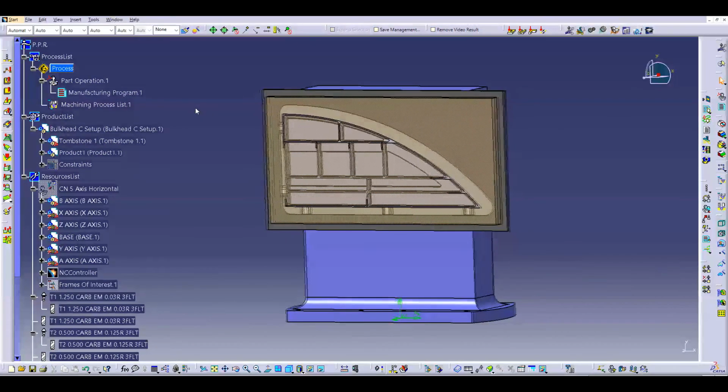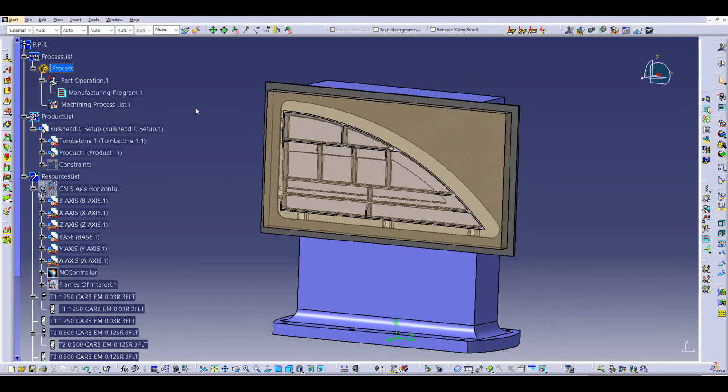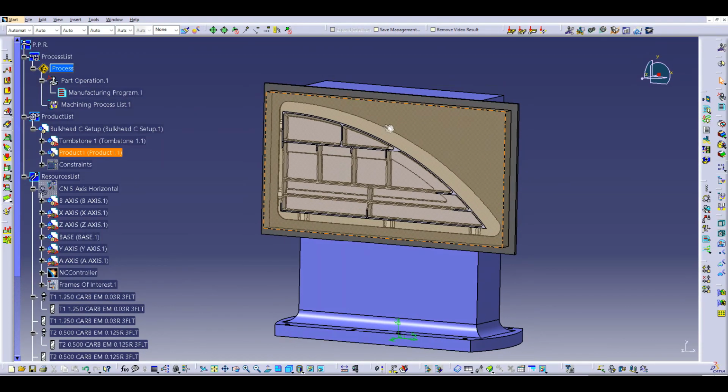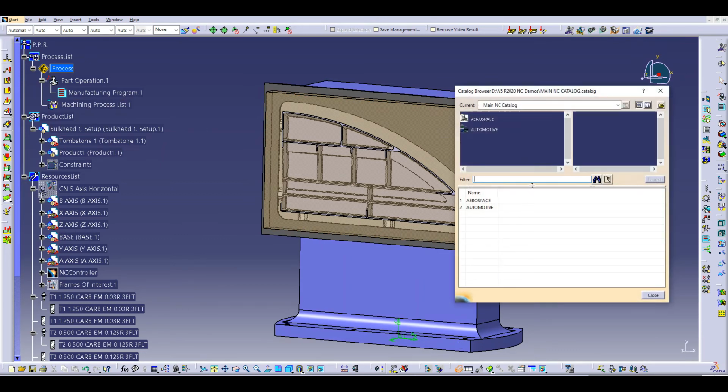But we don't need to go into the other application, so we're going to focus on our NC programming, and we're going to grab some knowledge-based NC by selecting our catalog browser. Knowledge-based NC allows you to capture and reuse your strategies and the way you like to machine parts. So when you have things that you know are proven, they work, all the settings that are in them, you capture them, you store them, and then you apply them later, so you're not having to refill out all this information every time you program.